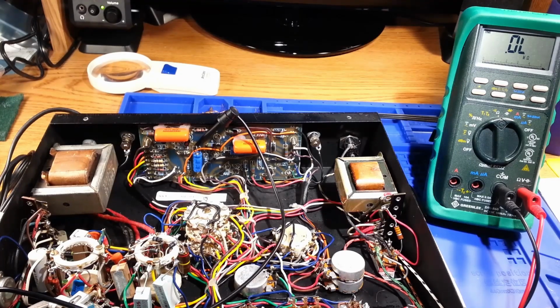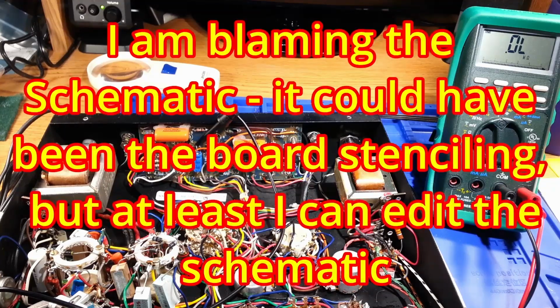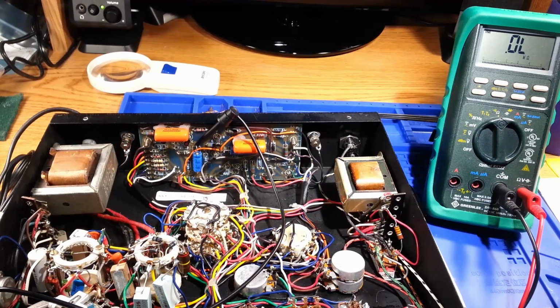And what I am finding out is that sometimes having an accurate schematic can be worse than having no schematic at all, because at least with no schematic, that will force you to sit down and do signal tracing and or continuity tracing through components, through resistances, as well as you can to find out your signal paths. When you have a designated schematic, you are expecting the markings for the components as well as the values to be accurate. And in this case, I am finding that that is not the case at all.